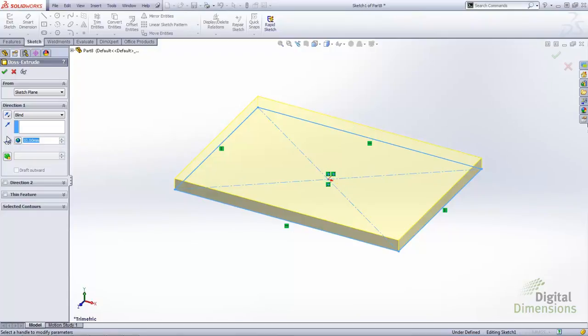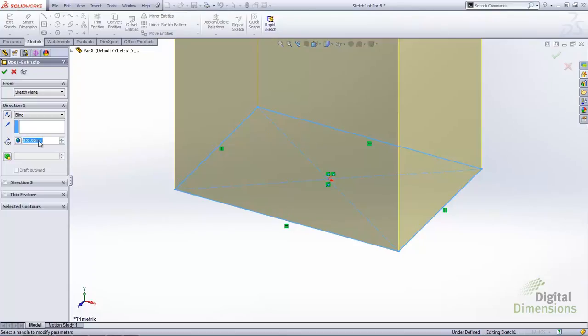There are many ways to set this global variable. You can either specify the size of the global variable, or you can utilize the control button, and using the mouse wheel will increment the variable by very large values. In reverse, holding the Alt button and the middle scroll wheel will increment by very small values. Incrementing with the middle mouse alone does the normal values expected.